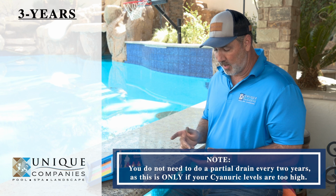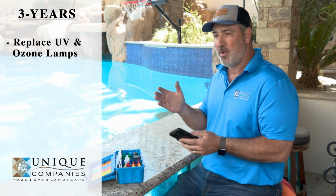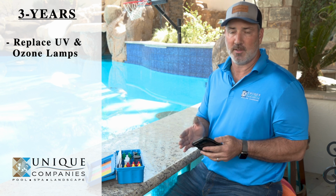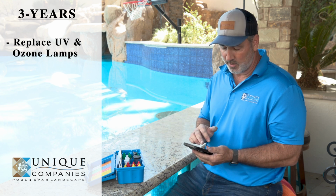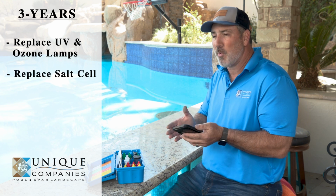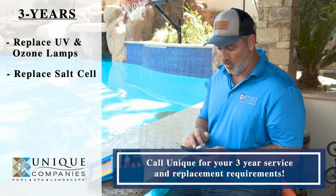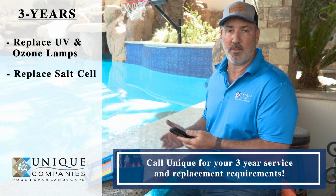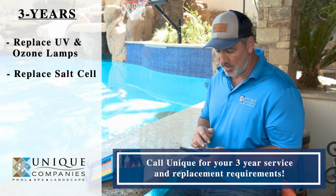And every 3 years, if you have systems like UV, ozone, salt, you're getting into the lifespan of those systems. So UV lamps and ozone lamps usually last 2 to 3 years. Your salt cell has a 3 to 4 year projected lifespan. So you need to start looking to see if those are working to 100% capability and start looking at replacement or service on them.